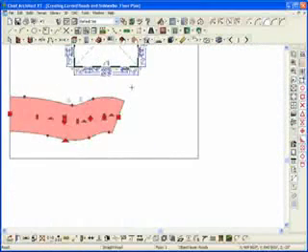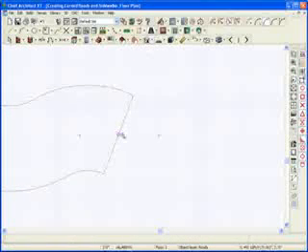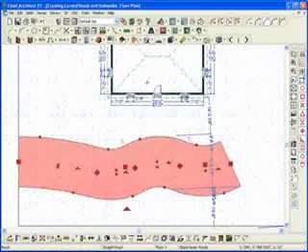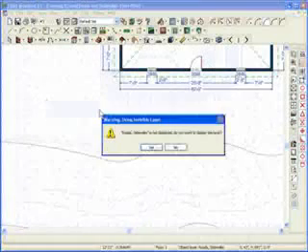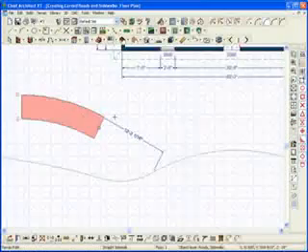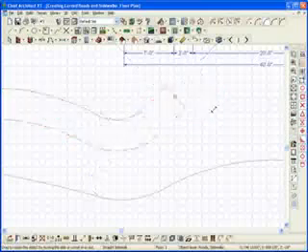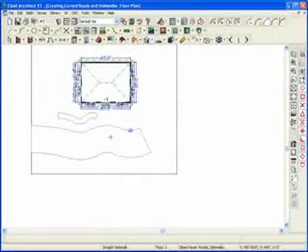So you see what I'm doing? The same thing I did with the CAD polylines before, I can do with roads. And you can do the exact same thing with sidewalks and driveways. If you choose the sidewalk tool, straight sidewalk, I could draw a sidewalk, turn that layer on, hold my Alt key down, Control key in version 10, add another one to it, bend it that way, add another one to it, bend it that way. So that's how simple it is to bend roads and sidewalks in your plan.